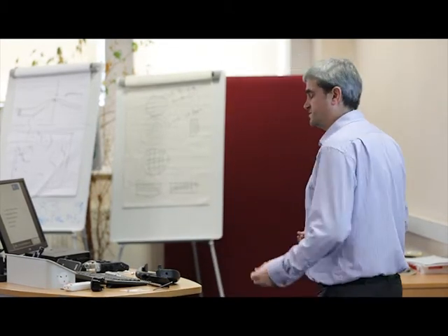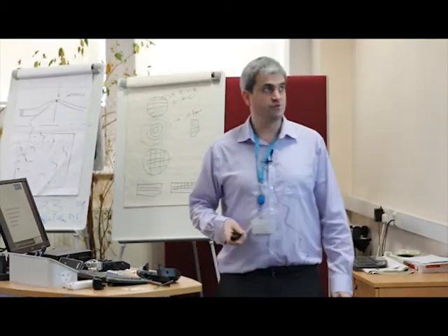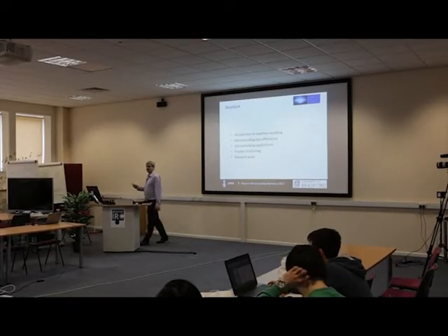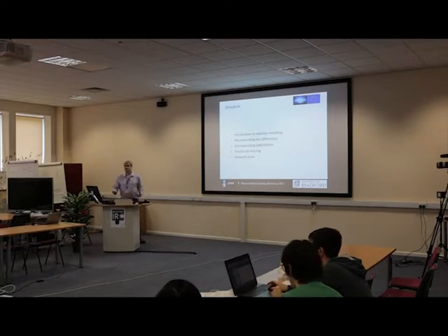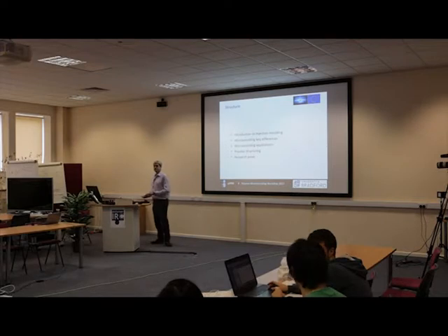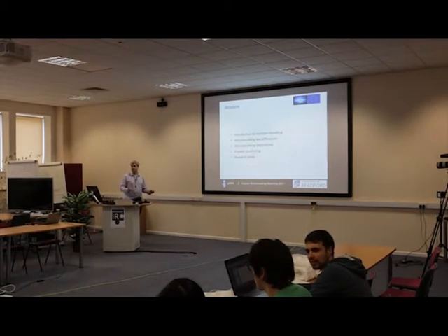And then we'll introduce how micro-injection moulding machines differ slightly from these conventional pieces of equipment in order to solve potential problems when using conventional injection moulding for micromoulding type geometries. We'll then look at some applications of micromoulding techniques, so areas where we're using micro-injection moulding capabilities to make very high accuracy structured surfaces, achieve very, very fine tolerances with different parts, and showing how we can use those in a range of markets for functional devices.